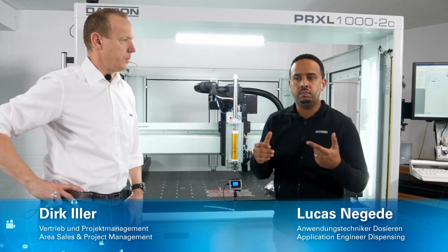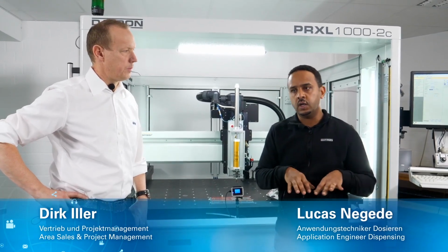This is the probe, a mechanical probe. Instead of the mechanical probe, we can use a laser or optical sensor to measure the surface and correct, to reduce the cycle time in this case. Additionally, we can add a plasma head to clean the surface of plastic or aluminum parts. This is pre-dispensing, so that means pre-positioning of dispensing. Before dispensing, we do the surface treatment. Afterwards, we dispense the material to have good adhesion between the material and the surface of the product.